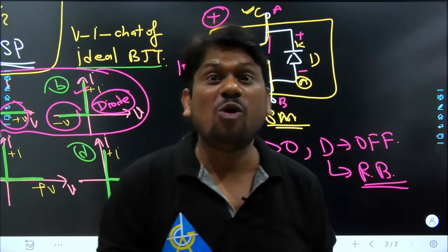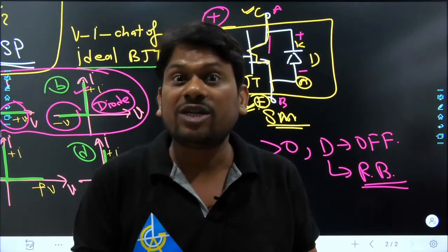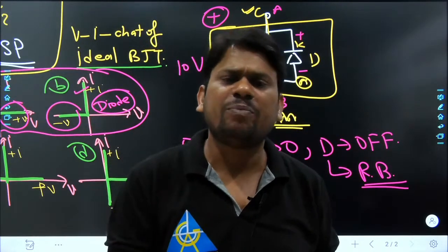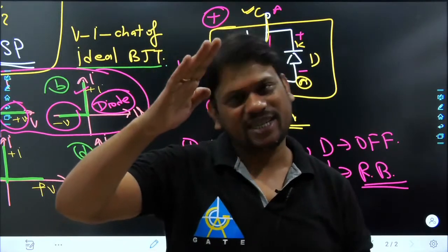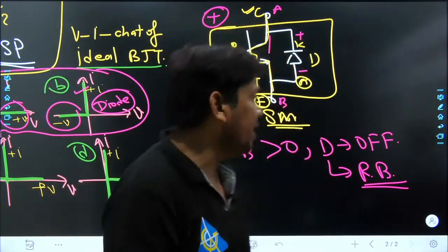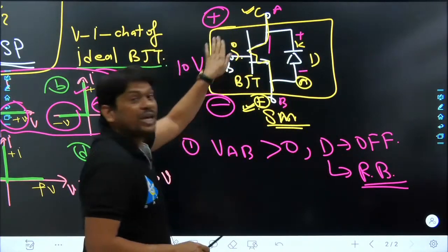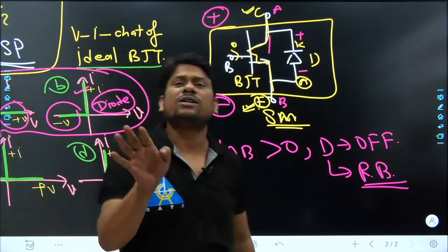Although, if you apply the base current, in other words, positive base current, definitely your BJT will get turned on if the condition is there, that the collector voltage is still higher than the emitter voltage. But unfortunately, at this moment, when we don't apply any base current, even though the collector voltage is higher than emitter voltage, BJT will not turn on anyhow.